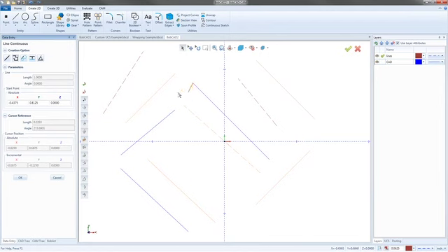If I want to make perfectly straight lines, first thing is I already have a snap increment turned on. It's all the way down here. It's where we set up this 0.0625, and that's our snap increment. So what's going on is where this line is jumping to, you'll see the line on my screen. I don't know how clear it'll be on your guys's, but if you can see where my cursor is currently sitting and then where the line is, it's not even touching my cursor. And it's not touching my cursor because my cursor is in between a point of, a 1/16 of an inch.